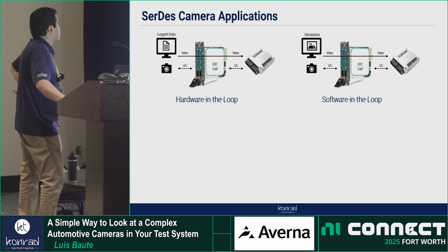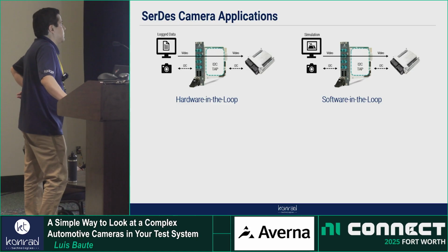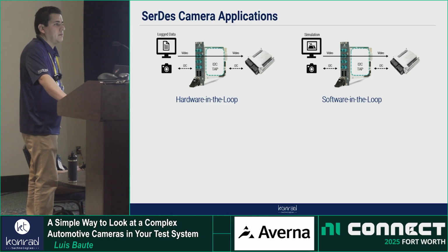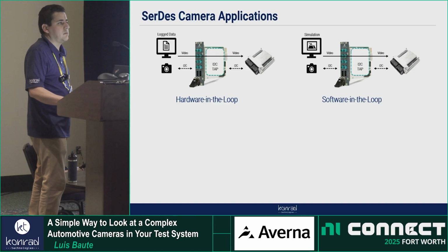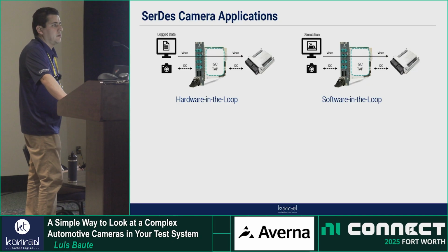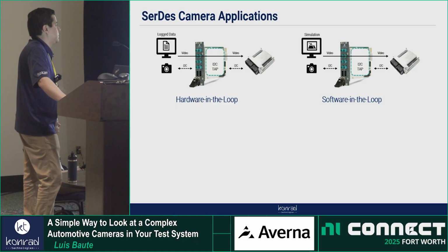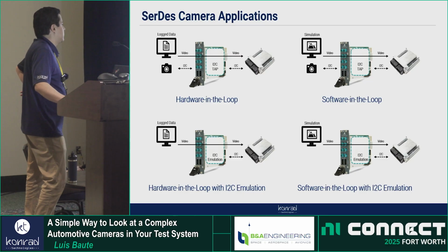So that is one application. The other one would be software in the loop, in which instead of getting images from the camera, you can just simulate them. We've seen that in some cases Unreal Engine is used. You've probably seen it, like the Call of Duty game was based on Unreal Engine. So this is just an example for it. And also I2C simulation.